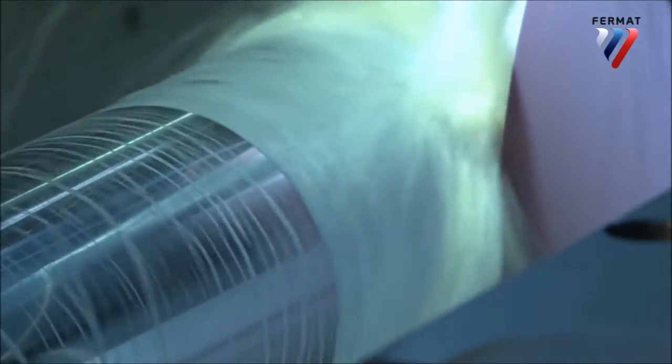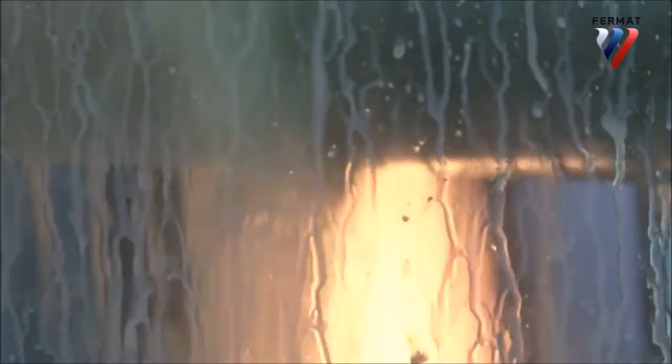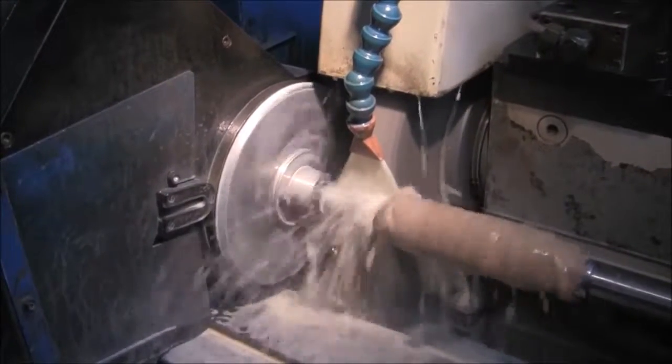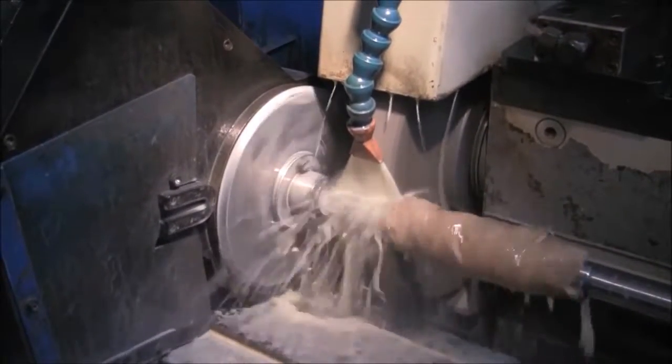Lubrication is an important aspect that is necessary in grinding. A large amount of heat is generated due to friction forces between the abrasive wheel and workpiece. This can compromise the part or even the wheel, and so proper lubrication must be utilized. Common examples of lubricant include coolant and different grades of oil.